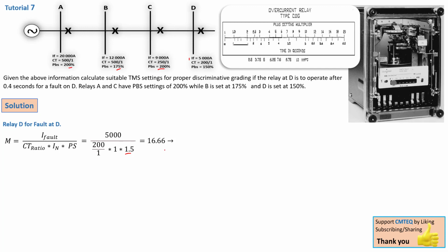Then what do we do with this M? We use this M to calculate your tripping time, TC. The tripping time is informed by the IDMT characteristic curve. Since they did not specify which IDMT characteristic curve to use here, whether it's very inverse, extremely inverse, or what have you, we have to use the normal inverse characteristic. The formula for the IDMT normal inverse characteristic is TC equals 3 over log of M here. So we then have to proceed and use that TC for the formula.